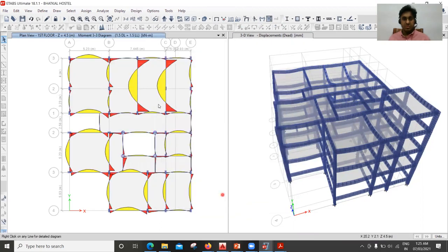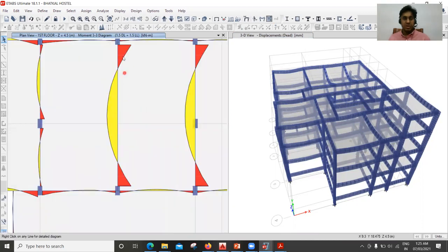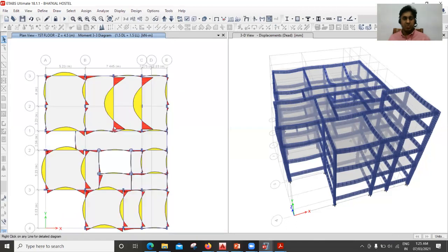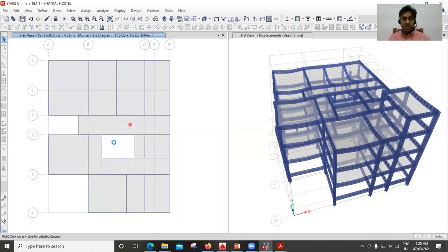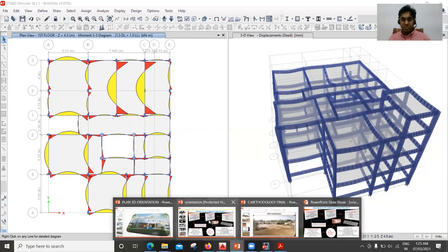You can see all these things we studied in our engineering days. That is a bending moment. At the support you get a negative bending moment. You did something like fixed end moments, then you get a sagging moment here, that is a positive bending moment. Again you get a negative bending moment. These things we manually did in engineering. Whatever we did in our engineering, the same practical things we are seeing here, how these things are applied in practical projects. Similarly for the shear force, everything we studied comes in the designing and the analysis part. Right, now going back to the same thing.